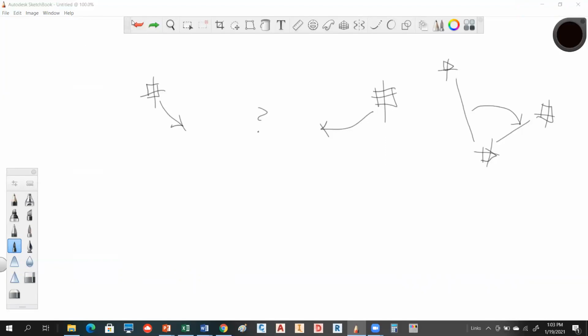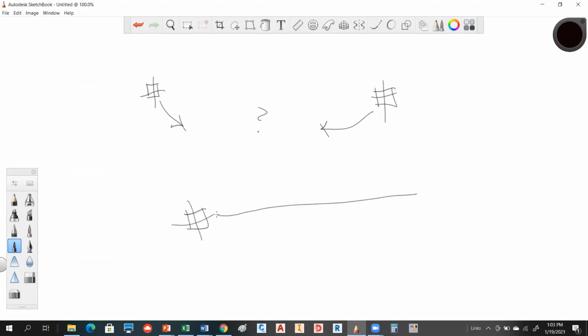So if we do layout, layout says that we typically have one fixed point, and we need to go out a certain distance. So let's say we go 500 feet, and we need to set this point at 500 feet out. This is an example of layout. You have a fixed point, you have a known distance, you probably also have a known direction, and we want to set this point. This point doesn't exist. So the difference here is that the point, or in this case the distance, doesn't exist. Those are examples of layout versus measurement.